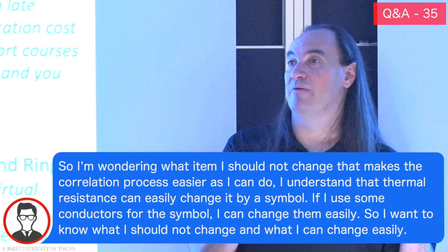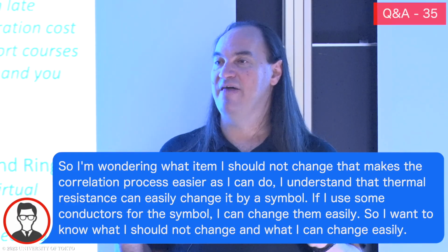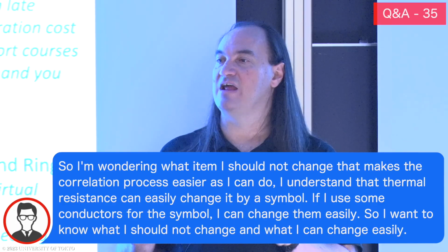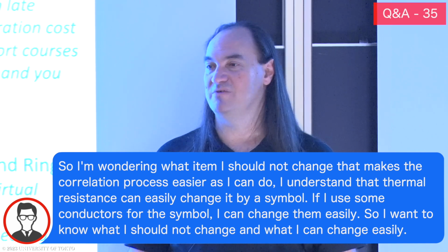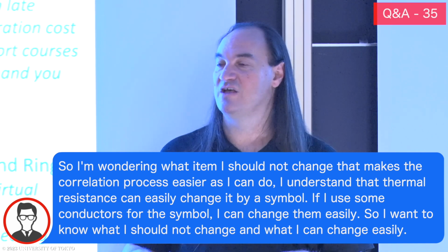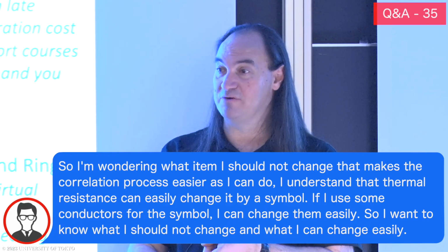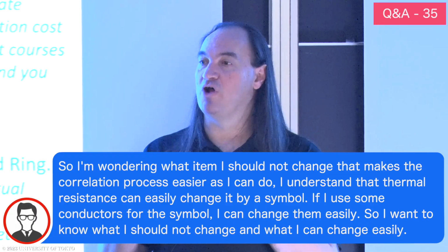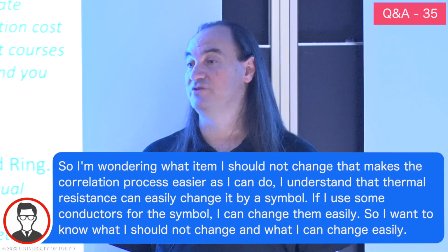So I would say wait until you have both hot and cold, or hot and cold and survival, and then start the correlation by just putting in everything that you know from the test. Don't make any other changes to the model, no adjustments to emissivities or conductivities or E-stars. Just put in, okay, I know all the powers, I know the environmental panel temperatures, I know this heater power. Put all the known knowns in and then start working to adjust the model to match.